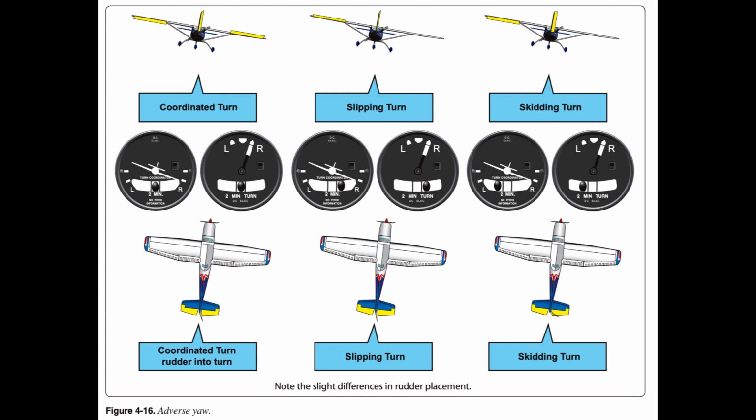An inclinometer, located in the turn coordinator or turn and bank indicator, indicates the quality of the turn, and should be centered when the wings are banked. If the ball is off center on the side toward the turn, the aircraft is slipping and rudder pressure should be added on that side to increase the rate of turn, or the bank angle should be reduced. If the ball is off center on the side away from the turn, the aircraft is skidding and rudder pressure toward the turn should be relaxed, or the bank angle should be increased. If the aircraft is properly rigged, the ball should be in the center when the wings are level. Use rudder and/or aileron trim if available.